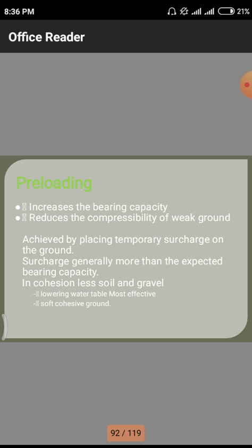If there is less distance, we need to remove whatever soil is present at the groundwater level and fill it with another kind of soil. Sometimes we need to use some plasticizers to prevent entrainment of water up to foundation level itself.